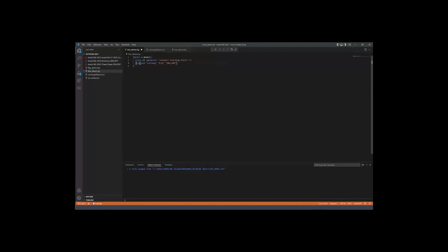So now we need to replace this starting coordinates here. This is what's called a fixed coordinate. This is hard coded, as we call it. So we're going to swap this out for the variable. Now variables you don't put into quotation marks, because quotation marks are used for putting what's called a string, or a series of numbers and letters, directly into the command bar.